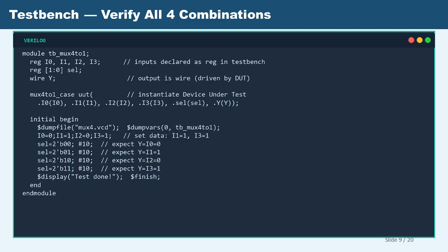Next, the test bench, okay. Next we are going with the test bench, okay. To create a test bench, we are going to create a module, and give a name to that module. After naming, you need to declare the components of that module, like what will be the input, what are the outputs, and so on. Look here, always in a test bench you are going to use wire for the output and reg for the input, okay. I will explain why we do it like this, okay.